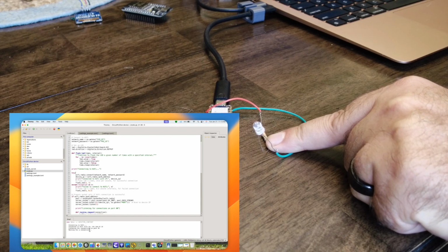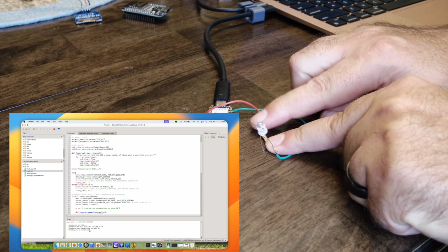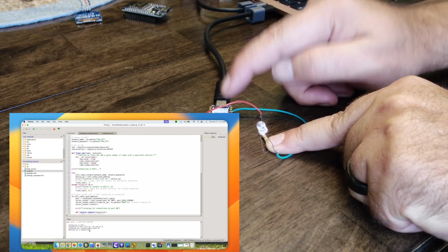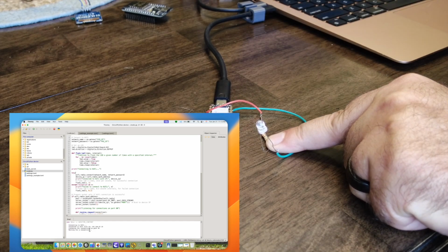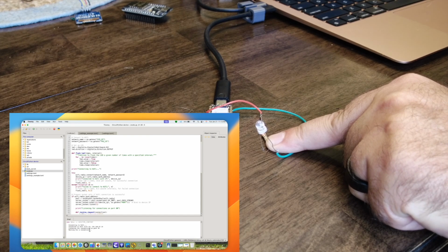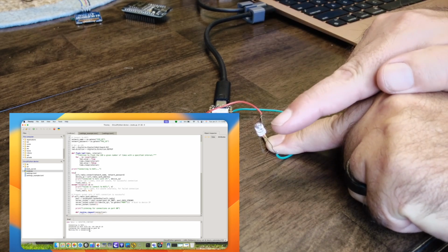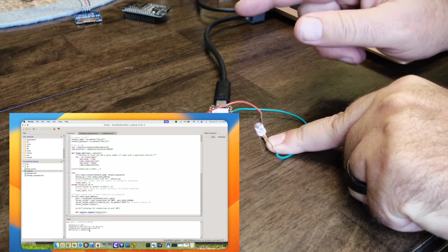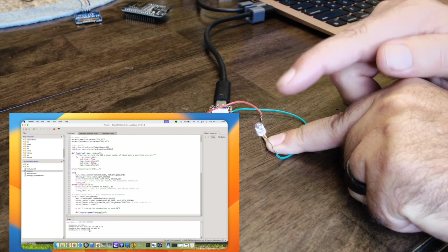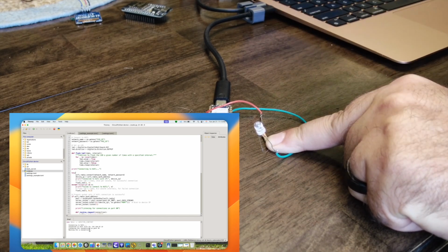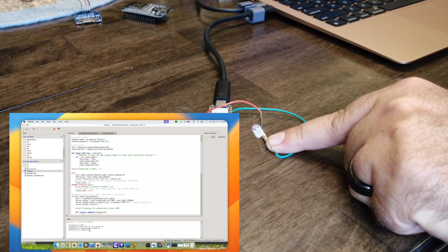Hopefully that makes sense, as I want to use the LED as a status light of what happened with the API server. If the API server starts up on this microcontroller, I will see the LED flash 3 times slowly. If it fails and it cannot connect, it will flash 5 times quickly. So that gives me immediate feedback.